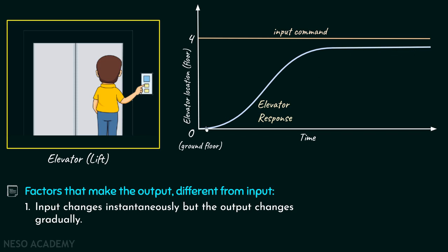We can say in this particular version of the graph, the control system is doing some work in order to generate an output. But in this version, the control system has done its work and it has generated the output. So we can say that this particular response lasts for a short interval of time in which any control system does some work in order to generate the output, and this particular response that lasts for a short interval of time is called the transient response in the language of control systems.